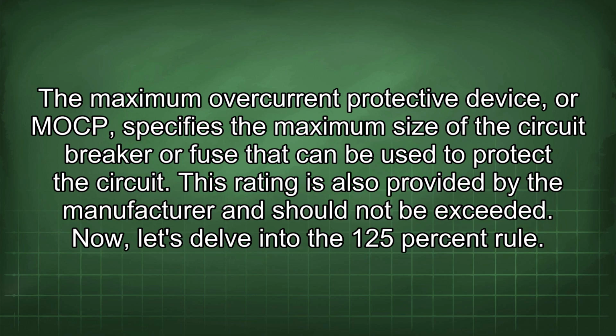The maximum overcurrent protective device, or MOP, specifies the maximum size of the circuit breaker or fuse that can be used to protect the circuit. This rating is also provided by the manufacturer and should not be exceeded. Now let's delve into the 125% rule.